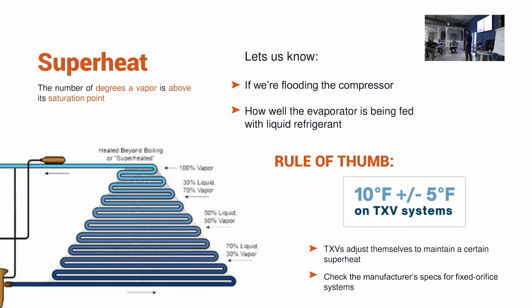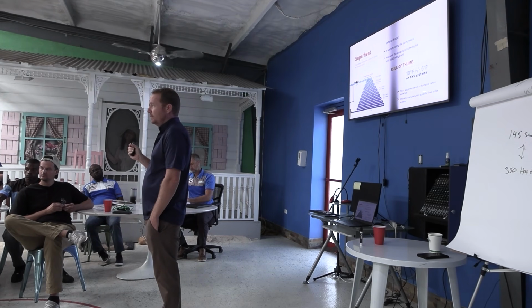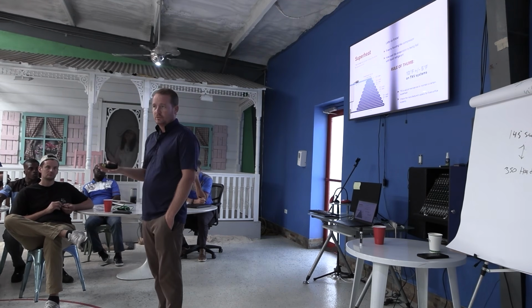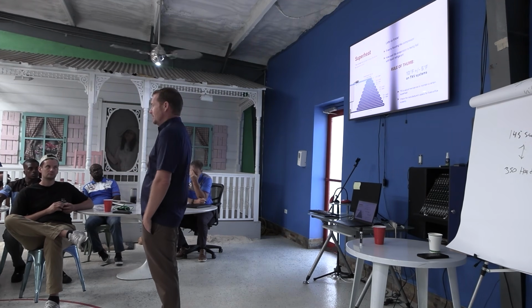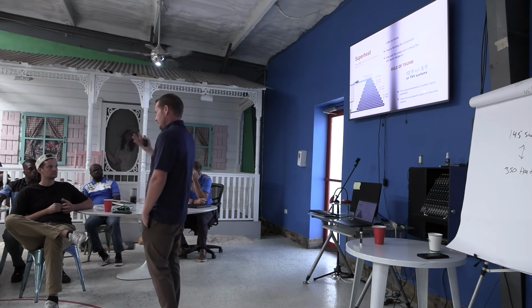Superheat comes down to what type of metering device you have. It's really important to know what type of metering device you have. And nowadays, do you guys see many piston systems, fixed metering device systems anymore? Still a few of them, yeah. We see a few of them now and again. And that's where, like a lot of new people, if you went to school, you were taught you charge the system by superheat when it's a fixed metering device or when it's a piston system. That's what they would say.